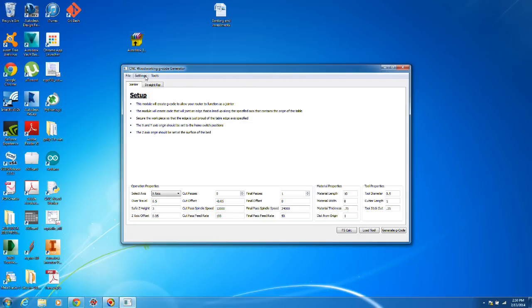The next thing you have to do is the grid, and I will be heavily using the grid in my woodworking system. Basically, if this was my bed, what I've set up is in my MDF spoil board, I've drilled a series of 1/2-inch holes in an array. They're on 1.5 inch centers that go in both directions. I think I have a little under 2,000 holes in my bed, but it doesn't take long for the machine to drill and bore out and precisely locate all those holes, so you can set up the same thing. I highly recommend that because it allows you to have a lot of freedom in where you locate your work as you're going.